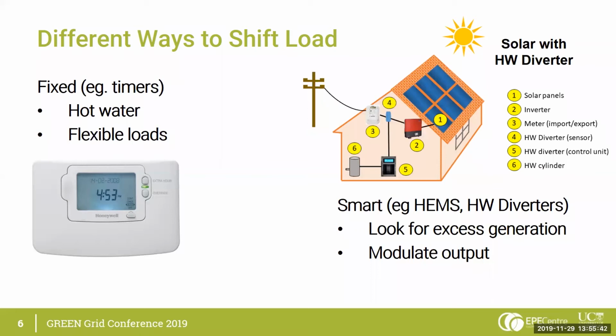So it's not suitable for all loads, but things like hot water, a simple resistive load, it'll actually modulate it using burst fire or pulse width modulation to reduce the load down to whatever you're exporting.